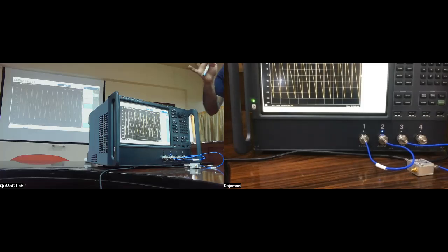So, okay, look, for the purposes of this, we have some two-port network, okay, which has 2 ports. Inside, it could be anything. It could be long cables, it could be long path lengths. That doesn't matter. What I'm talking about is that whatever response you get for that system is what you are interested in studying. In most practical cases, you will need some cable to connect that system to the network analyzer.